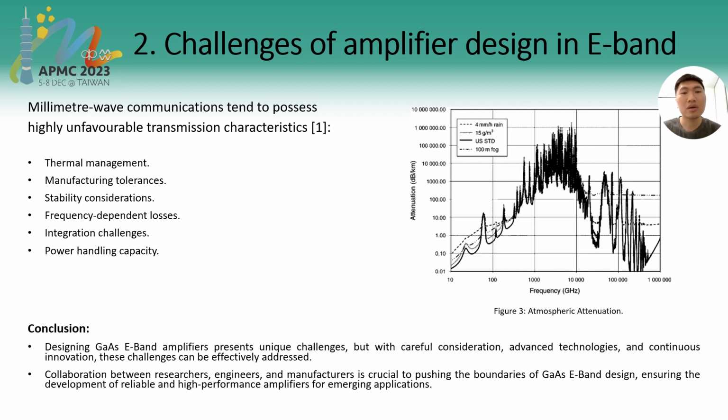The final challenge I found is the power handling capacity. GaAs devices may face challenges in handling high power levels without degradation. So to implement power control mechanisms, optimize the biasing and use power-aware design techniques to enhance the power handling capacity of GaAs components.